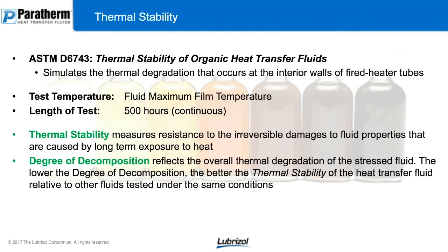Now, thermal stability is measuring the resistance to the irreversible damages. Now, that's important, irreversible damages. Thermal fluids, yes, while they can be filtered and while they can be recycled, when you really degrade a thermal fluid, those damages are irreversible because you're actually taking away from the thermal efficiency and the thermal values that that fluid is able to maintain. So these irreversible damages to fluid properties are caused by long-term exposure to heat. That's what this test is measuring.